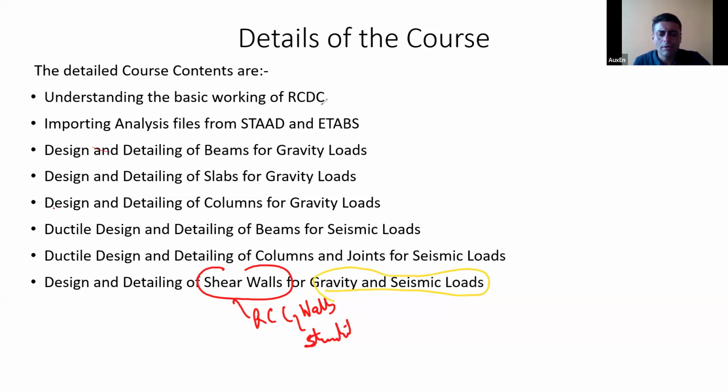I mean, obviously you can design RCC walls in zones or in locations where you are only doing it for gravity loads. But basically, if you are providing a RCC structural wall, usually it is to take care of the lateral loads more.